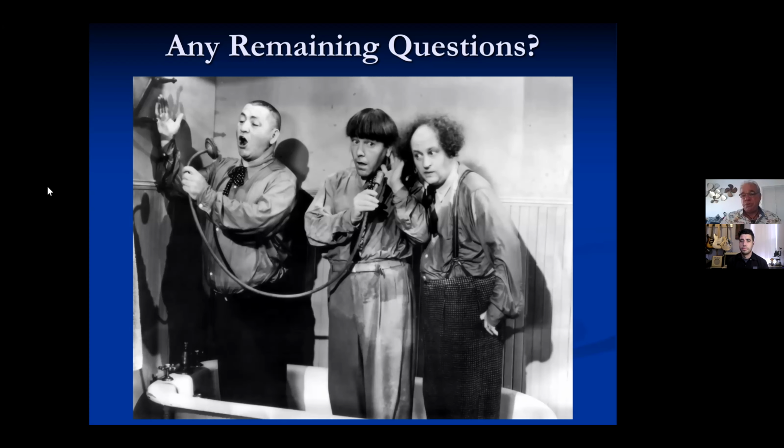As soon as you introduce an RF amplifier, you introduce noise, intermod distortion, you decrease your range, you reduce your audio quality in analog, and you create more dropouts in digital systems like a Sennheiser 6000 or a Shure AD. So I know I'm probably not making some manufacturers happy, because I already built them, but the bottom line is I'm not a big fan of antennas where you cannot separate the amplifier with a filter.